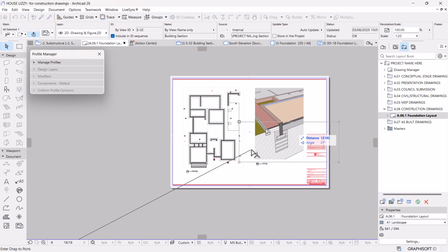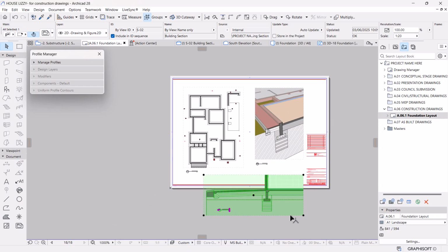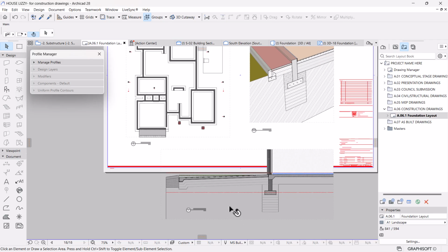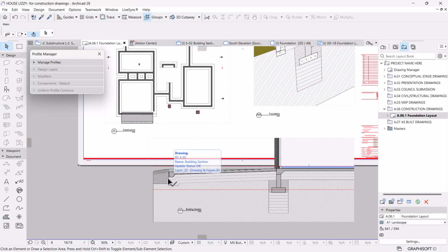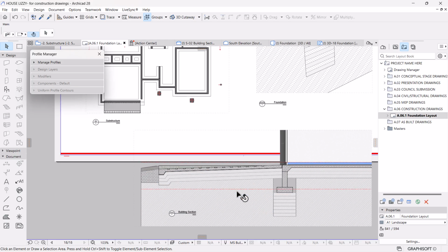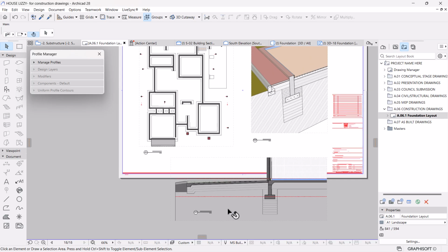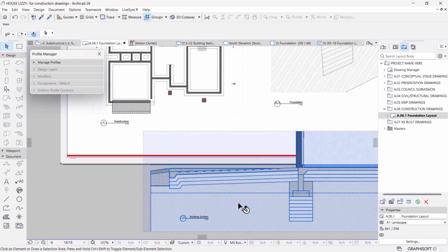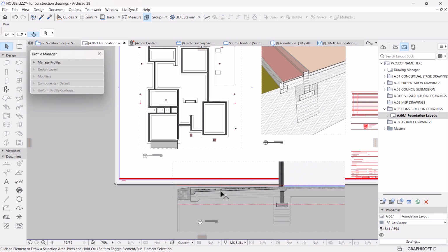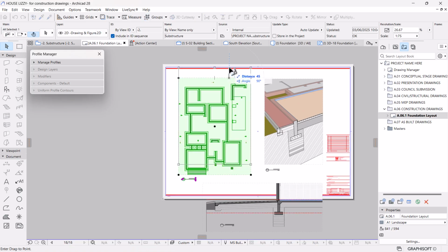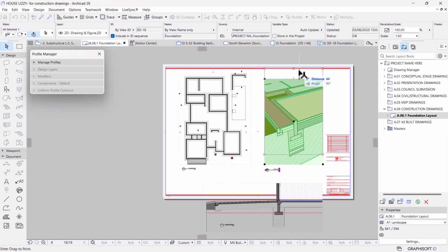You know, I could have used a detail tool. You know what the problem with the detail tool is? A 2D. You're converting this into a 2D material, unless you are certain you never change. But in this case, I'm not sure how the engineer will interpret this. He might have a different way of doing this, which is a better alternative to what I've proposed here. So I'll keep it as a live section because I can come back and modify this and update my drawings. Using a 2D detail will be a rework again. So I prefer to have it this way.